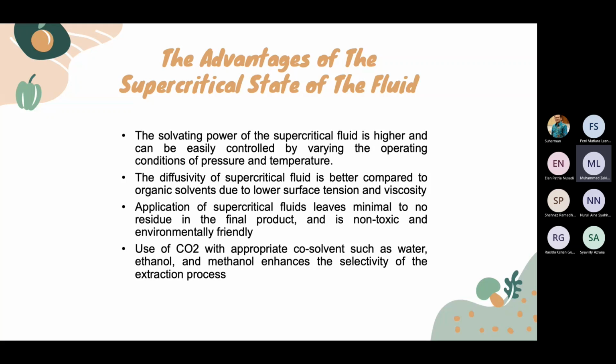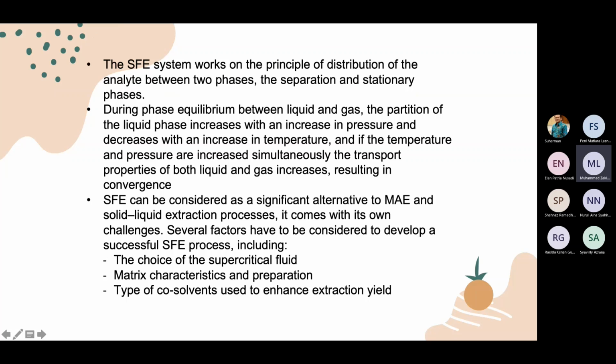Another one is use of carbon dioxide with appropriate co-solvents such as water, ethanol and methanol enhance the selectivity of the extraction processes. The SFE system works on the principle of distribution of the analyte between two phases, dispersion and stationary phases.